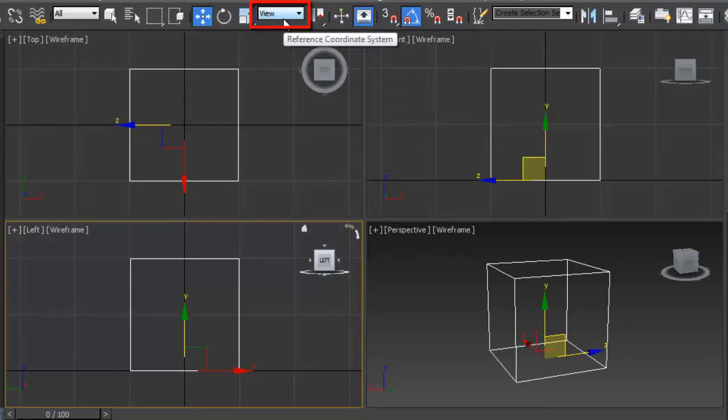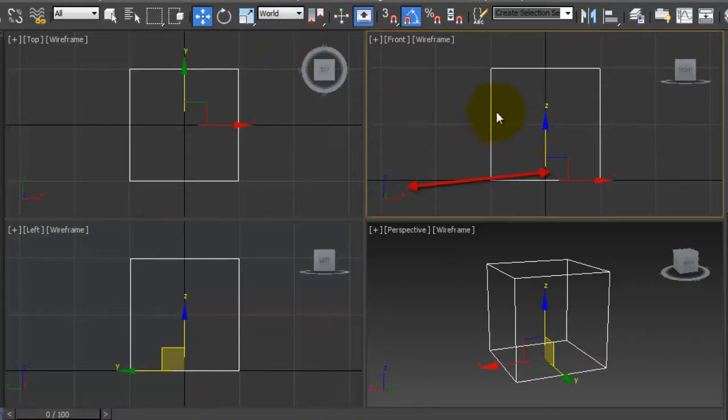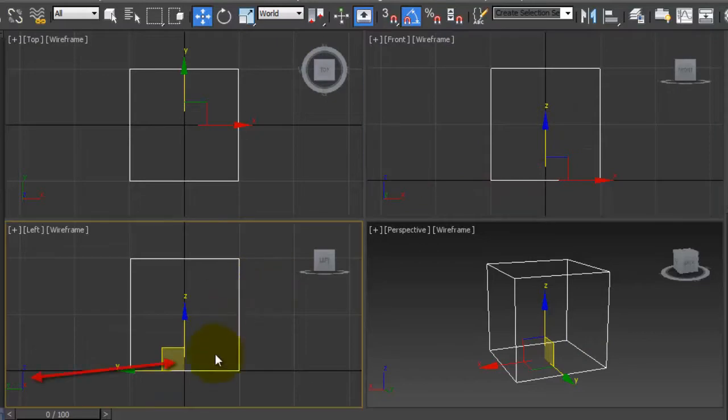By default, Max uses the view type, which identifies the axes XY as relative coordinates for the view that's active at any one time. It doesn't really change the axis, rather it uses XY for convention's sake. Let's say, if instead we want Max to always use the same reference axis for each individual view, we have to choose the word System. You can choose the mode that best suits you.